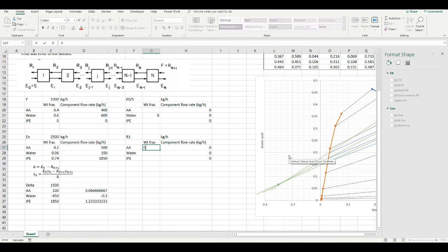So 0.295 and then 0.267, and this leaves the remainder. So now we know the composition of the raffinate stream. How do we use that to find the flow rates? Well, we know that the entering solvent stream contains no water, so that means that the balance of water needs to be contained within these 3 streams. So we have the extract stream and the raffinate stream that add up to equal the water entering from the feed stream.